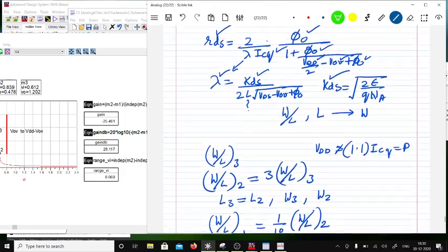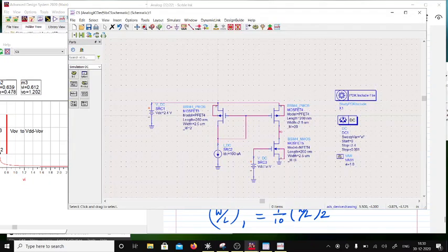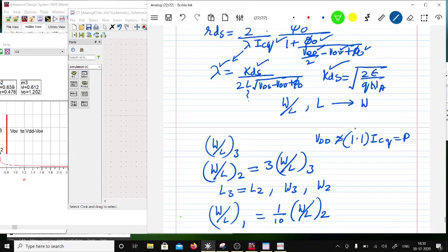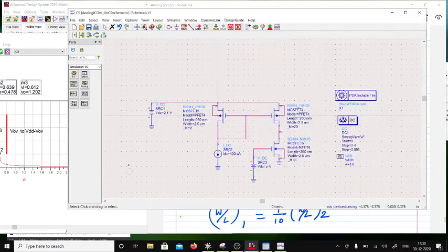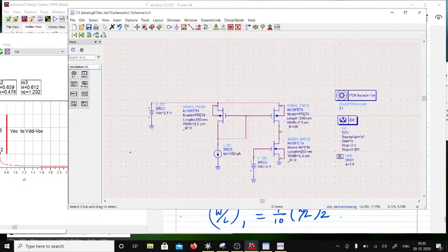Okay, so what designers do is trial and error. What I did at the start, I just did this trial and error, and I got the 25 dB gain. I can start the other way. I can start with power dissipation and swing and a gain, and then achieve the sizes. So both is possible. You can write a MATLAB routine to do synthesis. Just give it a gain and swing and power, and you'll be done with this.